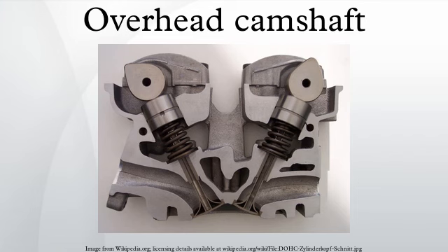Overview: compared to OHV pushrod systems with the same number of valves, the reciprocating components of the OHC system are fewer and have a lower overall mass. Though the system that drives the camshafts may be more complex, most engine manufacturers accept that added complexity is a trade-off for better engine performance and greater design flexibility.